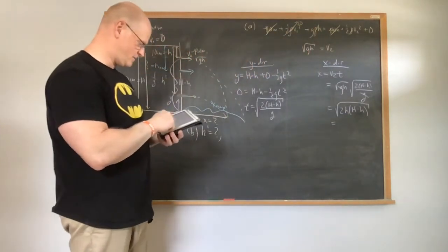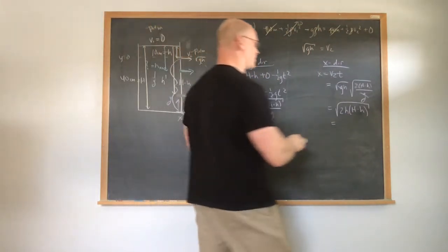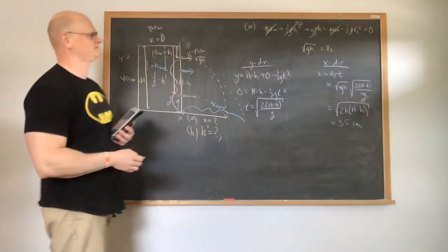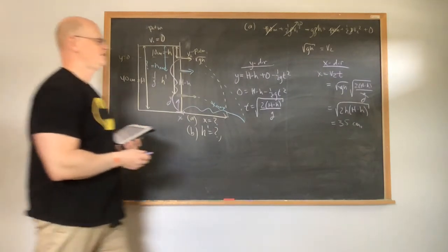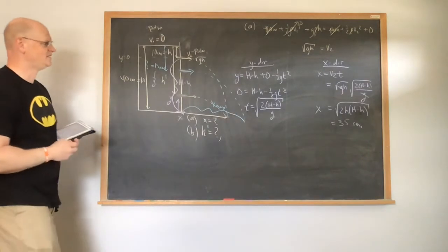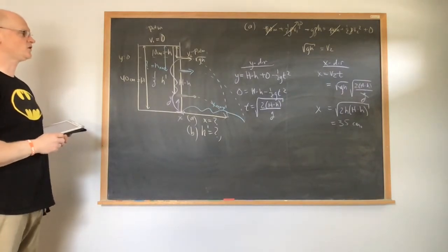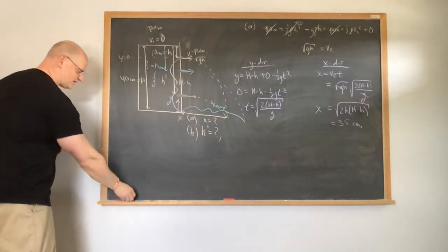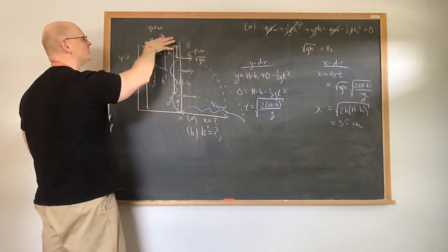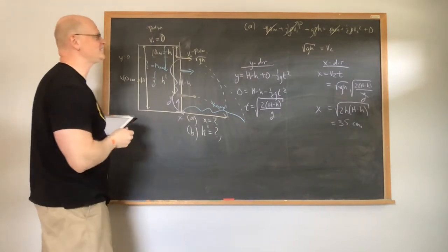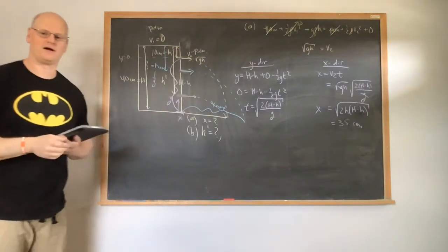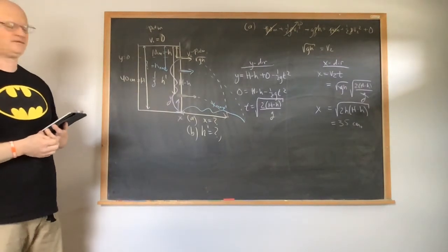So, plug in our numbers, we find in this case then is that this ends up going 35 centimeters to the right. Good. So x is equal to that. So that's part A. So part A, we're just using, again, the continuity equation, using the fact that, again, small cross-sectional area, large cross-sectional area, so this has to be zero velocity, followed by Bernoulli's equation, and then from there, projectile motion that we've done 1,000 times way back when.